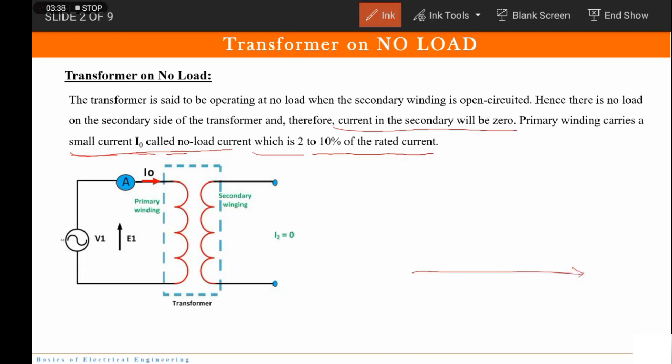So see, this was flux. This flux will lag the input voltage because it is in opposition, it will try to oppose. So the flux will lag input voltage by 90 degree. Now if this winding is ideal winding, then we should get I0 here, 90 degree lagging.